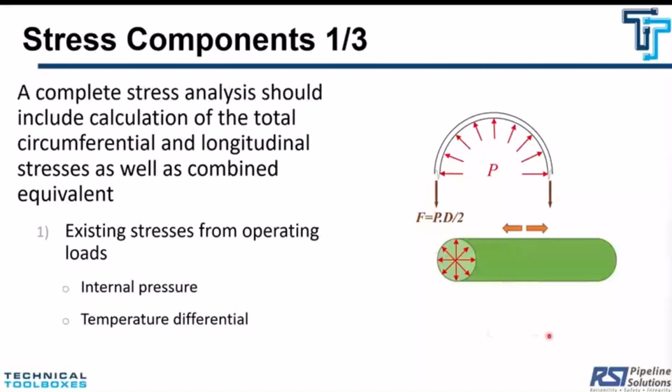When you pressurize the pipe, because the pipe is restrained longitudinally, and this diagram schematically shows the situation, this green pipe over here, when you pressurize a pipe that's buried, the pipe wants to expand in circumference because of the internal pressure. As a result of the Poisson ratio action, it wants to shrink longitudinally, right?